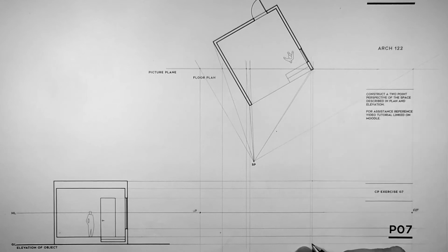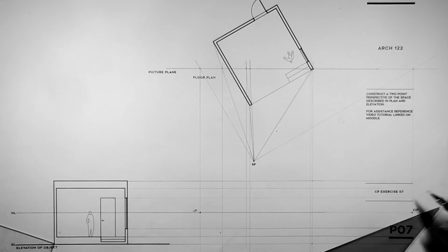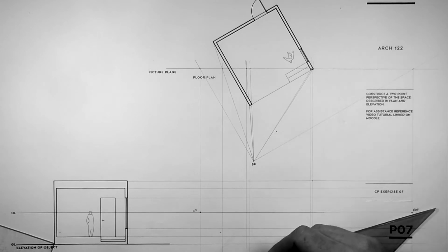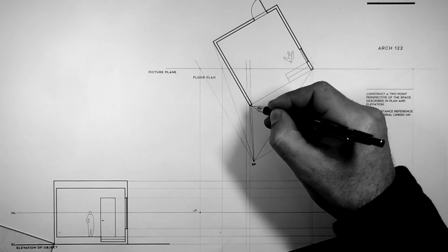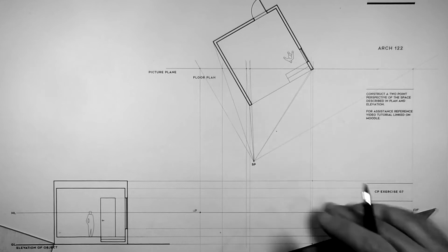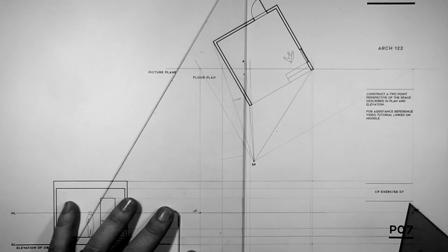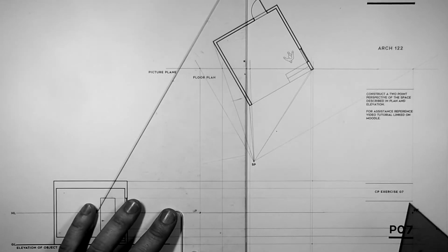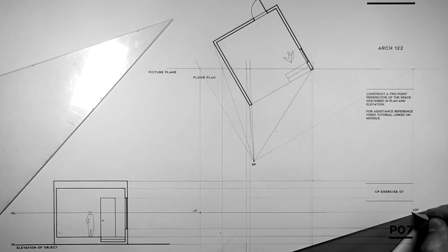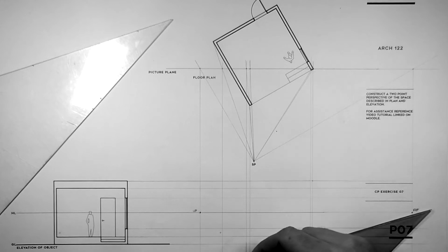So at that point, we know our building rests on the ground there, and from it, we can then connect a line through the right vanishing point. If it begins there, passes through that dot, and comes to this line, which happens to be the projection of the inside face of that wall. We actually need to go to the next one, which didn't quite bring it down far enough. So let's just extend that a bit more. So from the right-hand vanishing point through that point, we'll come all the way to there.